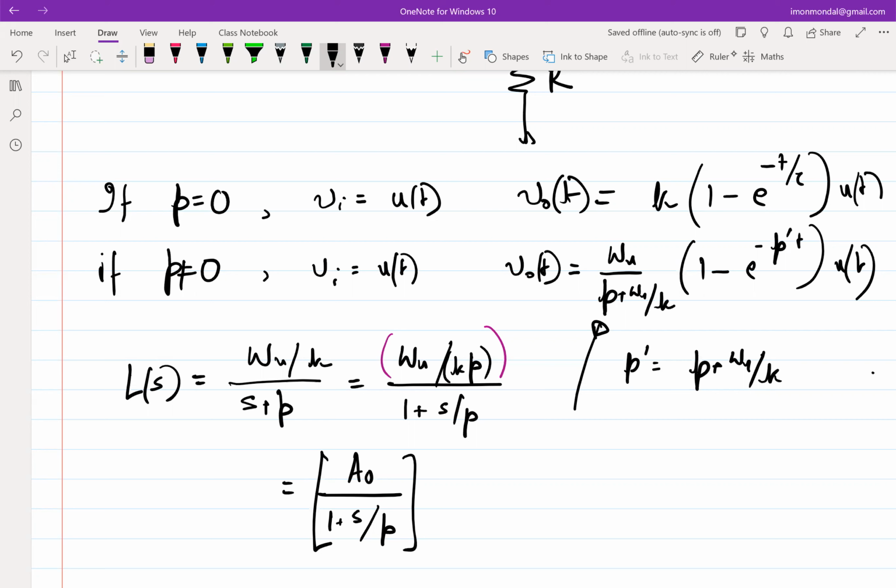So if I have moved by a factor of 10 on the x-axis, how much have I moved down on the y-axis? Pardon? 20 dB, right? 20 dB in terms of absolute means a factor of 10, right? You don't seem sure. You should be able to rattle these numbers out in your sleep. So this should be A0 by 10. Right?